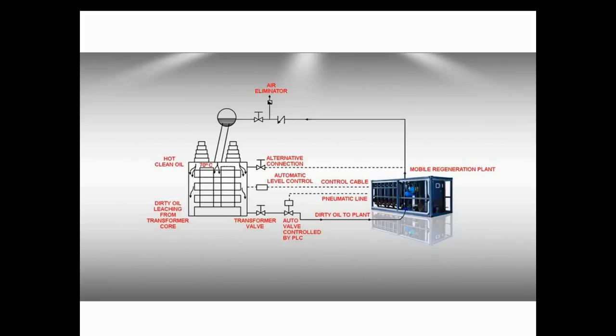We have a protection also. We install a pressure device in the transformer. This device measures oil height up to the conservator. The automatic valve is connected to the oil regeneration machine as well. So, if there is a problem at site, pipelines loosening or a problem in the machine, the oil level will drop and the pressure sensor will measure this decrease.